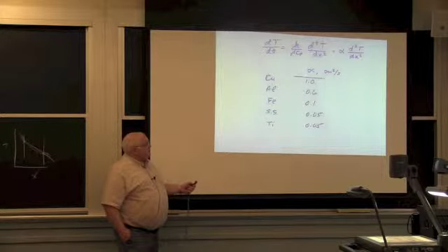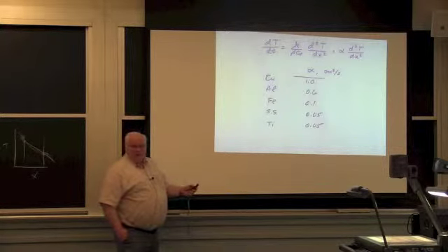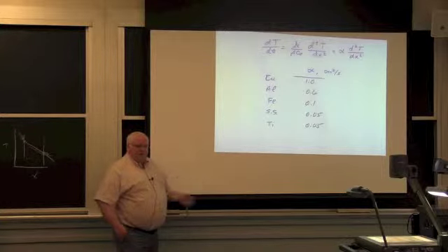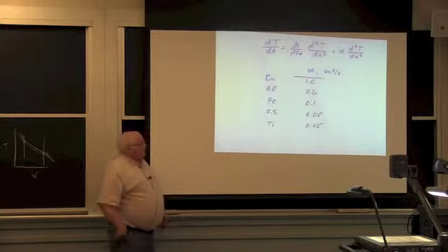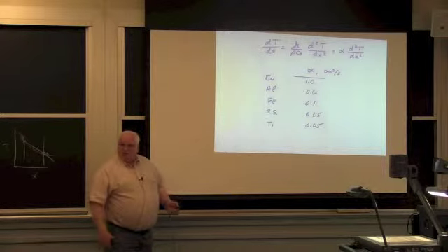The thermal conductivity is different than thermal diffusivity, and most people don't tabulate thermal diffusivity because it's a derived quantity from these 3 more fundamental quantities, and so usually you have to go and calculate it. The only text I know is I put a table in the welding handbook because we're always dealing in welding with transient heat flow problems.